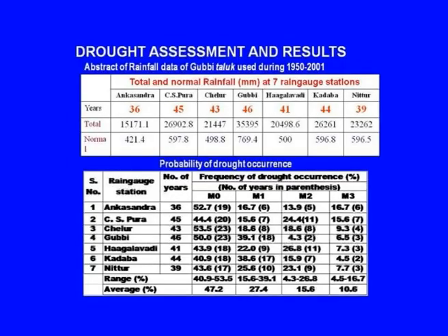So, for each year the rainfall which has occurred, we can make an assessment as to what is the departure of the rainfall, and on the basis of this the assessment of different regions within the study area can be carried out, wherein we can say what the rainfall is for given areas. Here the rainfall information is available as per rain gauge stations. So, based on the rain gauge station locations at different points, the normal rainfall condition has been derived.